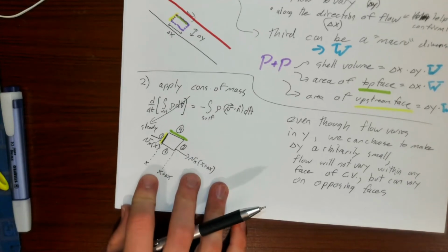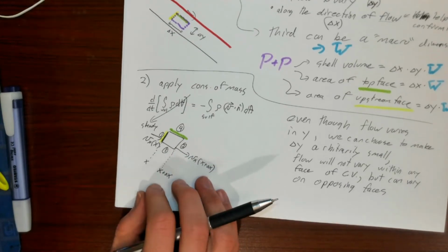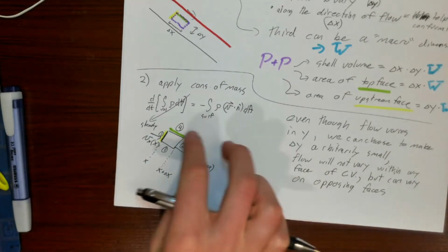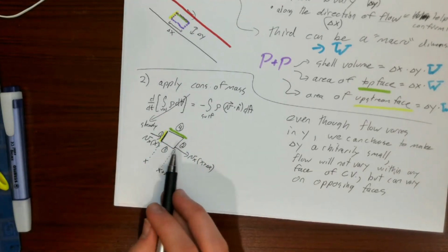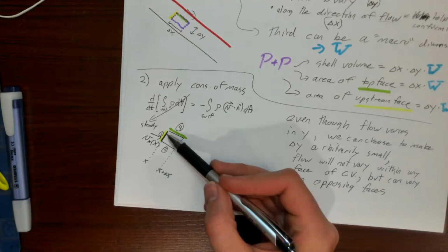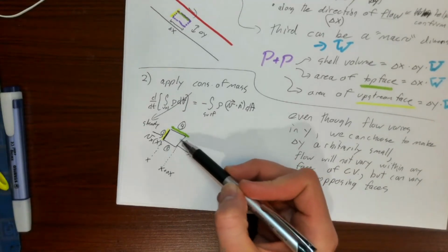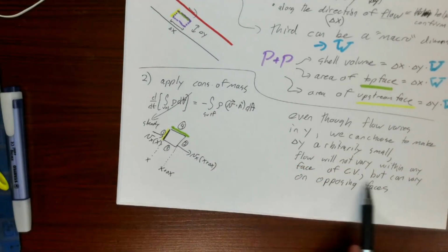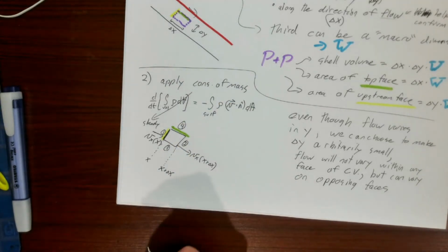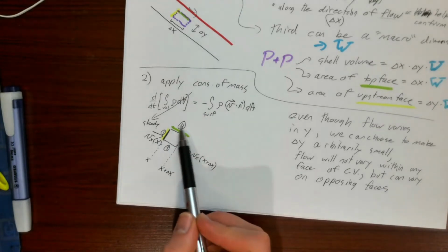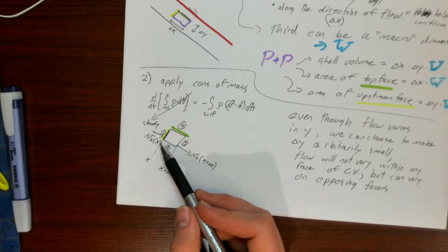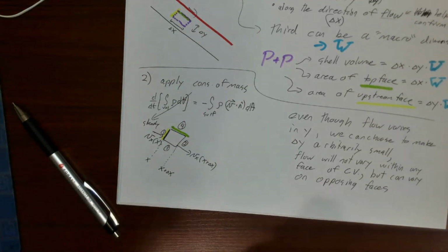The math people have given me a handwritten and stamped approval that the calculus works. So we're basically going to say these two velocities could be different from one another, but we're neglecting any velocity variation on a particular surface. So this is the plan. Now we're going to apply conservation of mass. So if I'm applying conservation of mass to this thing right here, take a moment now to pause and ponder.